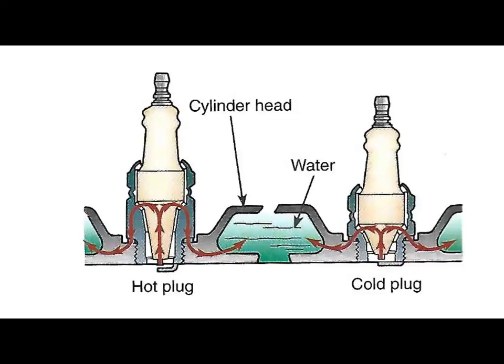The spark plug shell is sealed to the cylinder head opening by a metal gasket or a tapered seat on the shell. The spark plug heat range indicates the ability of the spark plug to dissipate heat from the center electrode to the spark plug insulator to coolant circulated through a cylinder head passage surrounding the spark plug. Hot spark plugs are designed with a long heat path, so the heat has to travel further up through the insulator before it is dissipated through the shell into the cylinder head and coolant.